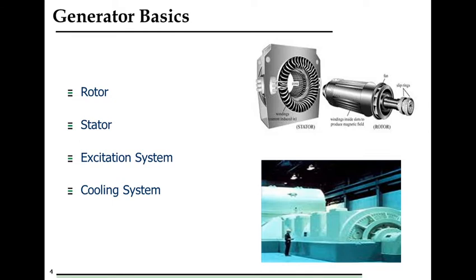If the field winding is on the rotor, low DC voltage can be transferred safely to the exciter winding via slip rings. The armature winding can be braced well to prevent deformation, because there would be a high centrifugal force if it was in the rotor.